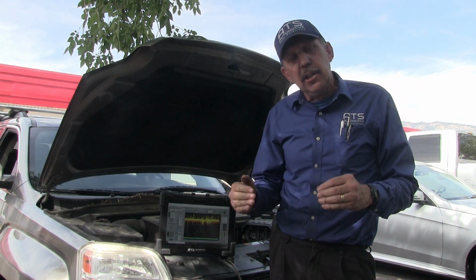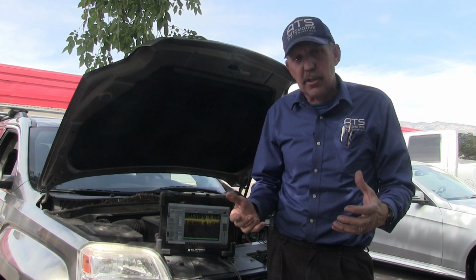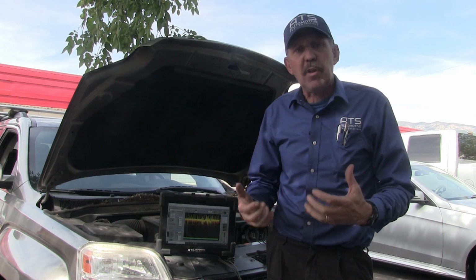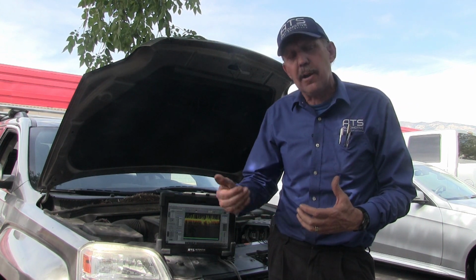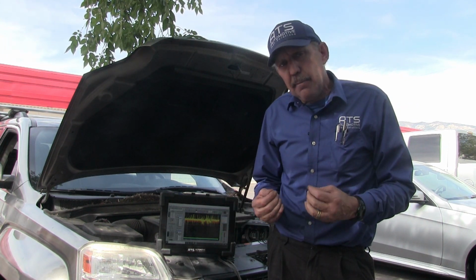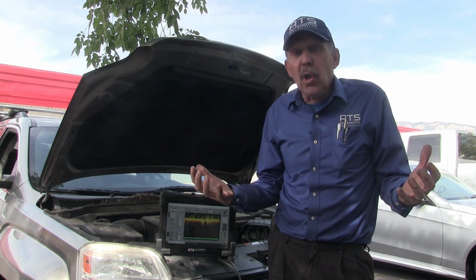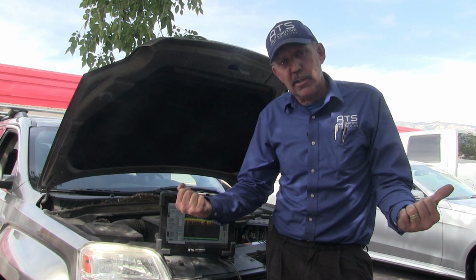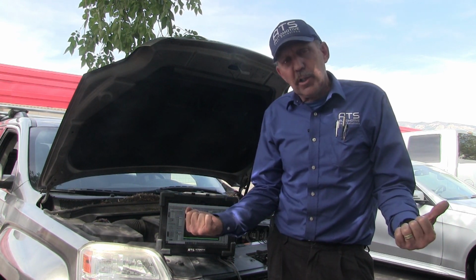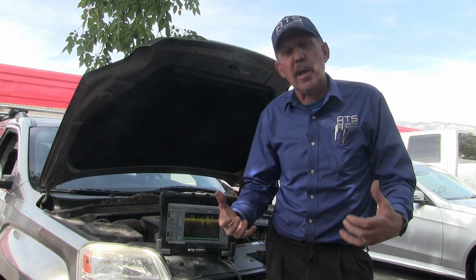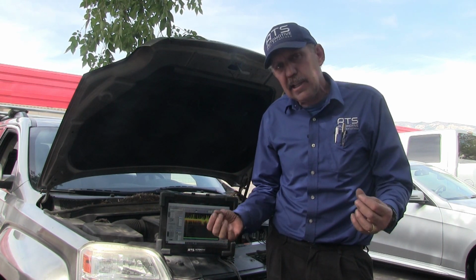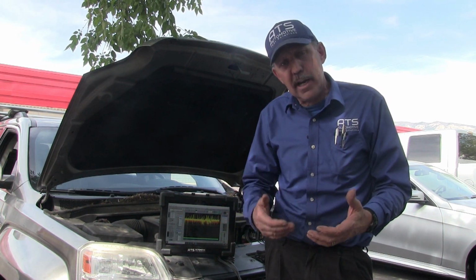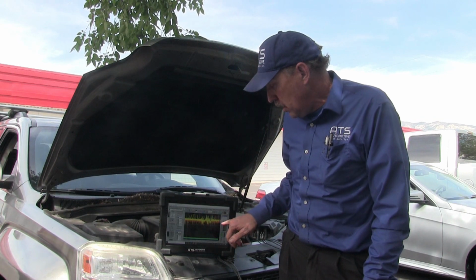Anytime I have a low voltage state on a sensor like an oxygen sensor or a TPS or an APPS or some type of sensor that doesn't generate very much current, the first thing that I'm always interested in is, is anyone pulling that current down? In other words, if the O2 has a problem or the computer has a problem, it'll pull that voltage down because there's no current in the circuit. There's only a potential change with very little current. So if anything has a path where that current can be drained off, it would pull these down.